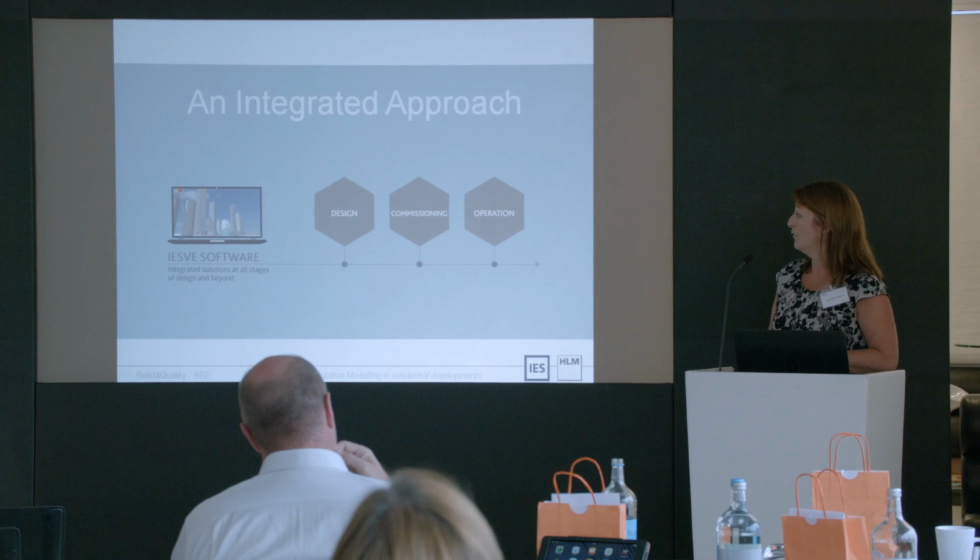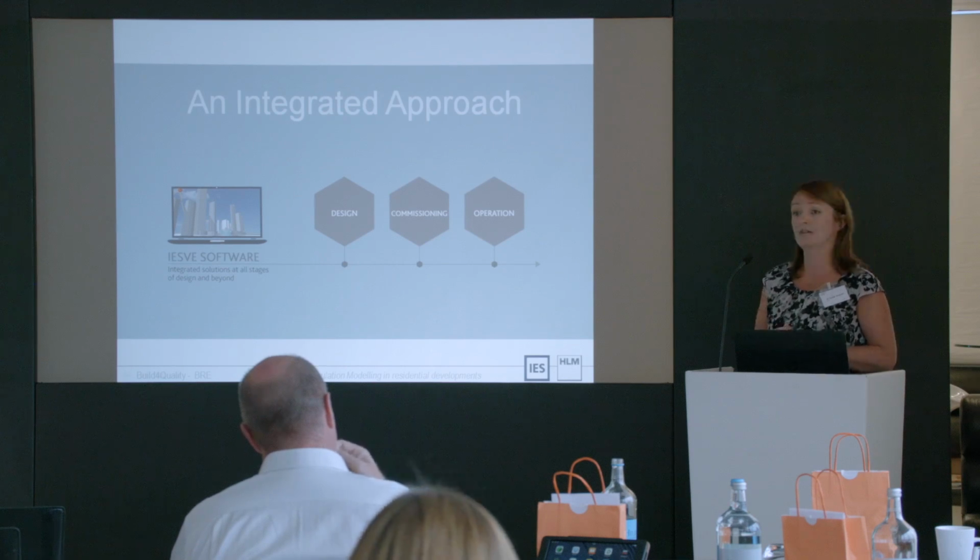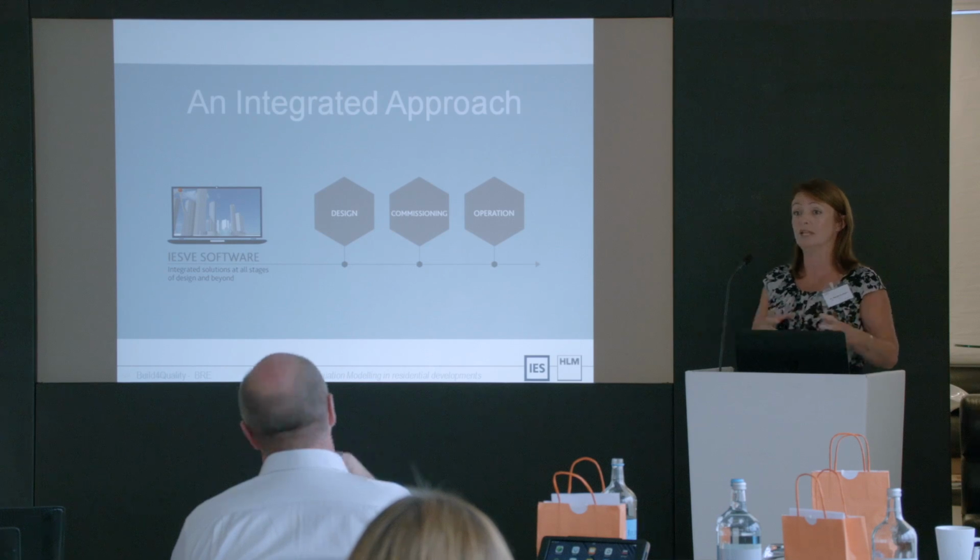But the focus now, I think, for us and for the industry is in the operational phase of buildings, because we can say day one, handover, this building performs to this level. It's got a Part L rating of whatever it might be, an EPC rating of B or C. But actually 6 months into the operation of the building or after 5 years, what does that look like?